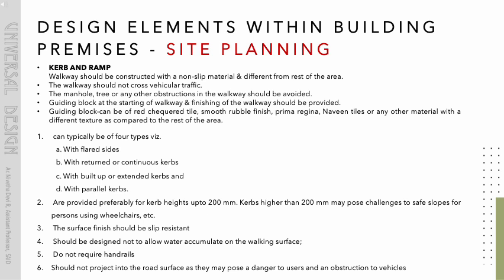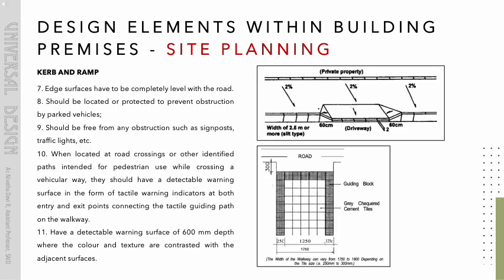The surface finish should be slip resistant. Should be designed not to allow water to accumulate on the walking surface. Should not project into the road surface as they may be hazardous. 7. Edge surfaces have to be completely level with the road. 8. Should be located or protected to prevent obstruction by parked vehicles. 9. Should be free from any obstruction such as signposts, traffic lights, etc.